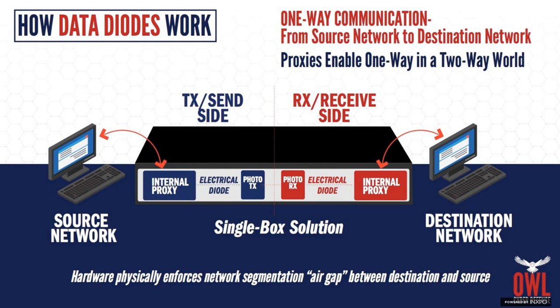So let's say you had some malware that got introduced inside the facility. Somebody walked in with a thumb drive, innocently or not, and they needed to put some software on the inside. Unintentionally, some malware gets released inside the plant. Now, a lot of that stuff will phone home and ask, hey, what do you want me to do? Across the diode, because there's no routing information, there's no routing across the platform itself, there's no way for that device to ever phone home.